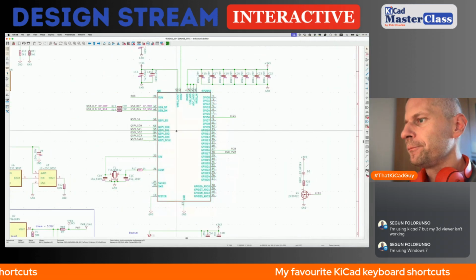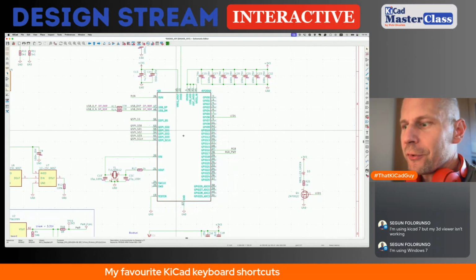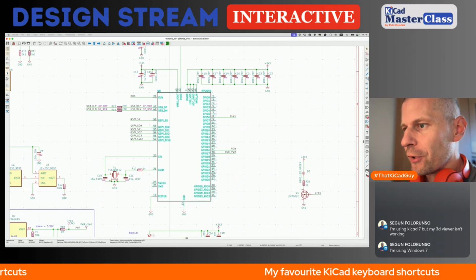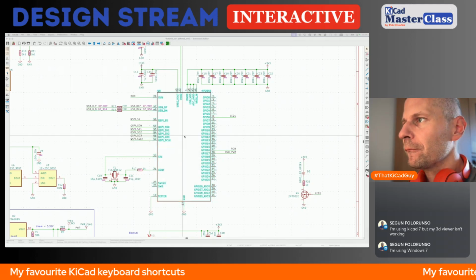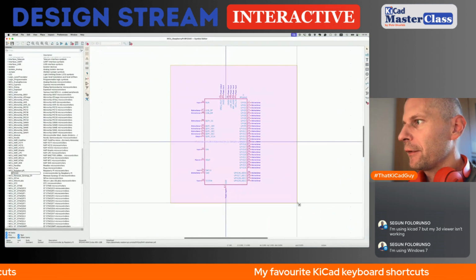So I will open the property window. It's not a favorite shortcut, it's a crucial shortcut. KiCad doesn't work without the E, so E is properties for the symbol. I'm going to open the library symbol.